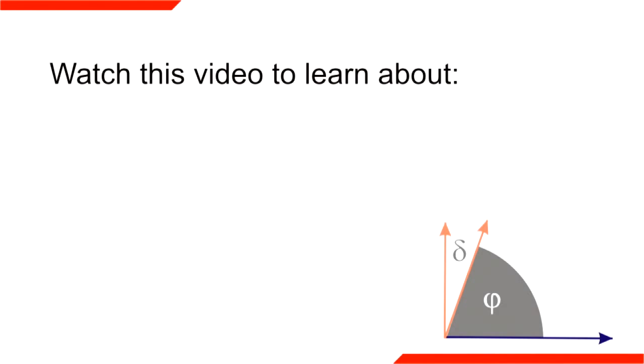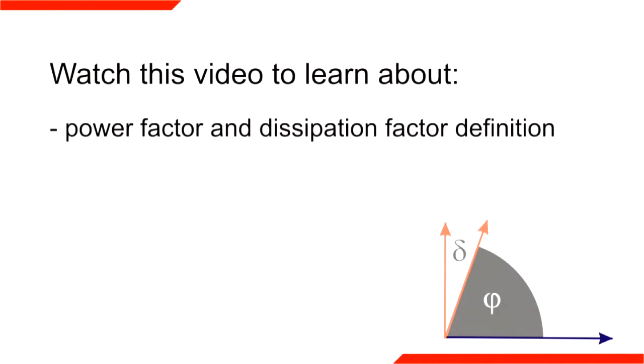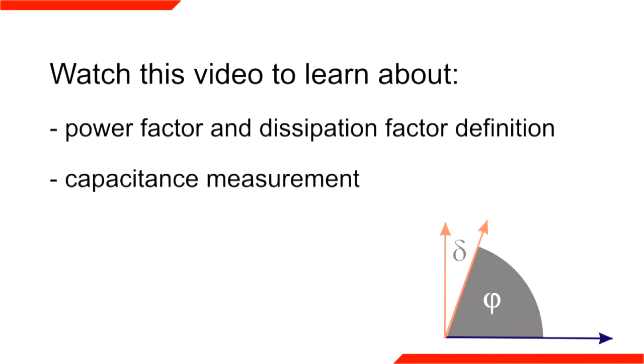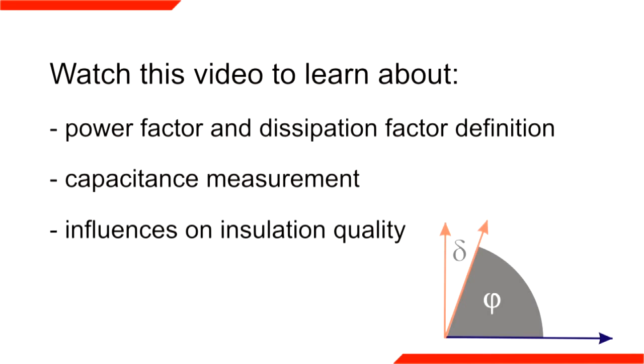In this video, you will learn about means to measure the quality of the insulation of power transformers and bushings, such as power factor or dissipation factor measurement, and measuring capacitance. Possible causes for a reduction in insulation quality are also explained.